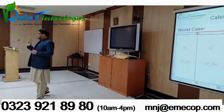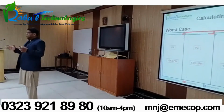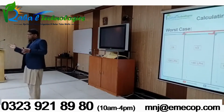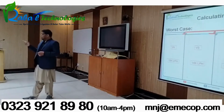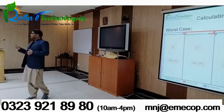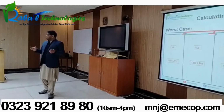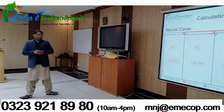Third is the specific gravity, but I'm not mentioning it here because by default we are assuming that we are dealing with water. If you are dealing with kerosene, petrol, honey or diesel, we need to take into account the specific gravity of that fluid in order to determine the pump capacities. But by default, we're dealing with water, so its specific gravity is 1, so no problem.